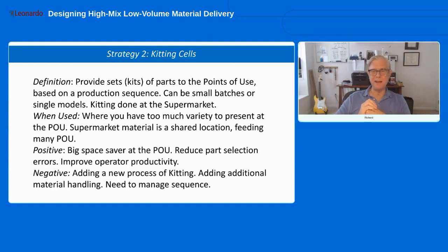The negative is that now you have a new process called kitting, right? So you've got to staff that process. You have to train the people. You have to set that up. You have some additional handling that you have to do. Also, you need to manage the sequence.